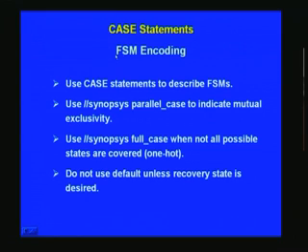And regarding writing an FSM, it is a state machine as such, and you can use case statement, of which we have already seen a couple of examples before. Use case statements to describe basic finite state machines, and this also we have already seen. Synopsys parallel case indicates mutual exclusivity, and full case is for when not all possible states are covered. As for instance, for a one hot machine you can use this here, and do not use default unless you want a recovery state.